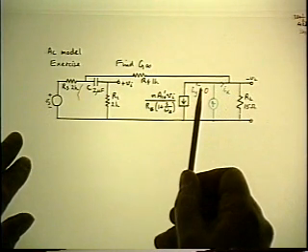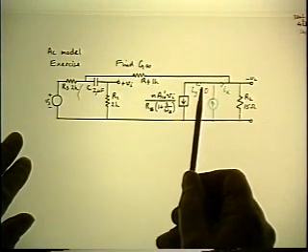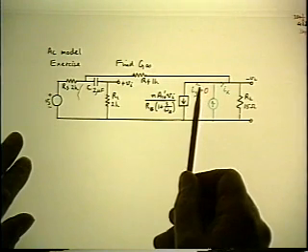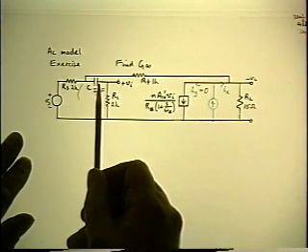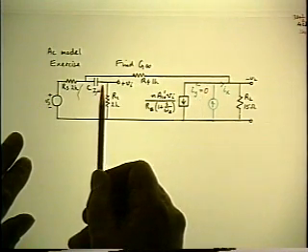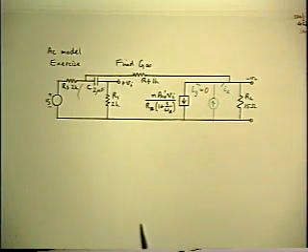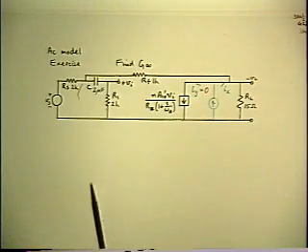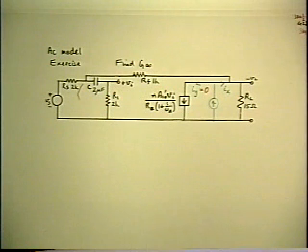And the reason we choose to do that is that if you null the IY, it propagates back to the input and nulls the error signal. And we know from the original definition that the nulled error signal is the condition under which we get the ideal closed loop gain g infinity, because it simulates infinite loop gain. So that's all you have to do.